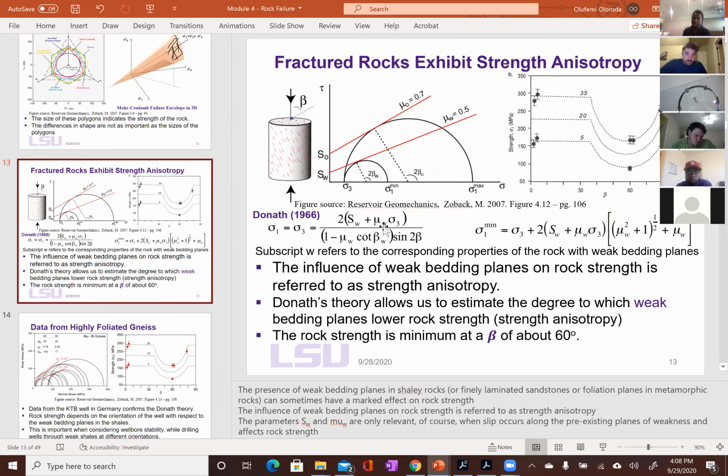And this is the reason why it's 60 degrees, which we were talking about before, right? Intact rock, you create a fracture, it tends to be along the 60-degree line. When you create the fractures, the strength of the rock is now different. It's much weaker. For the weak rock, the line is lower, meaning the intercept is lower. And because the intercept is lower, the circle you can draw under it is smaller. And that severely restricts the strength of the rock. So now it's much smaller.